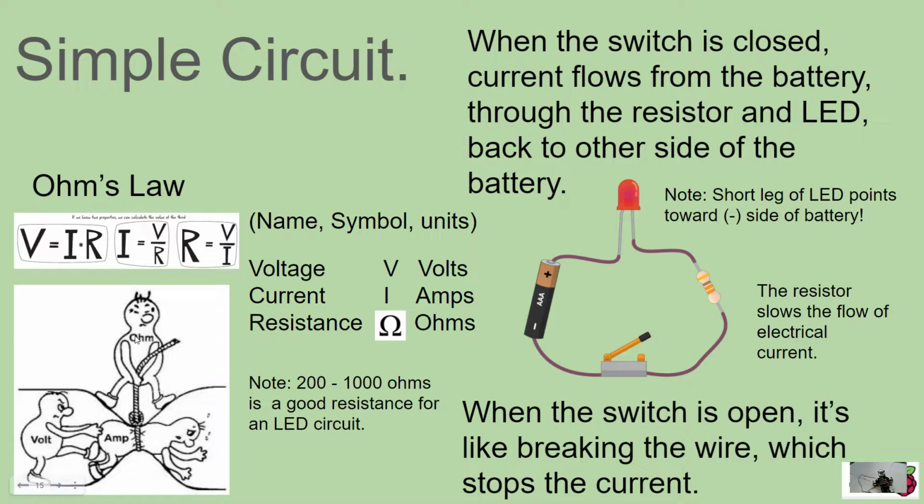But the greater the resistance, the bigger the ohms, the more the resistance constricts the flow of electricity through the wire, the less current is going to get through. And that relationship is called Ohm's law. Here I represents current, V represents voltage, R represents resistance, and the current is equal to the voltage divided by the resistance. For example, if you had a 6-volt battery and you had 2 ohms of resistance through the motors and the circuit, then you would get 3 amps flowing through the motor.